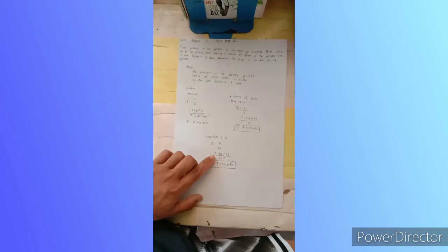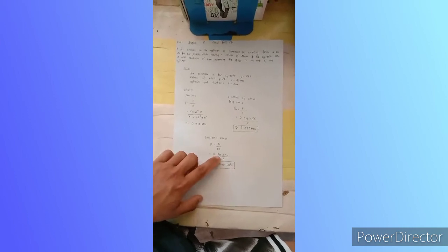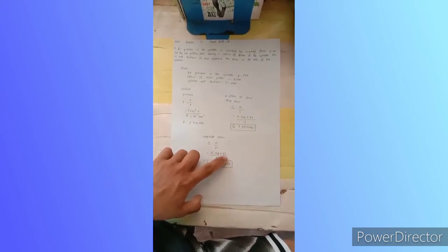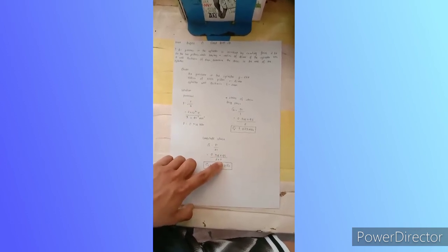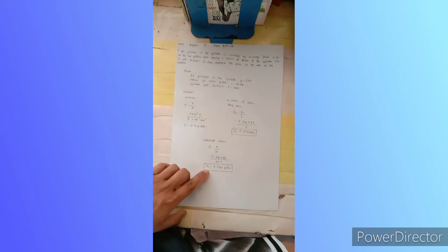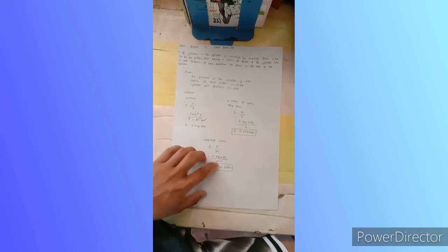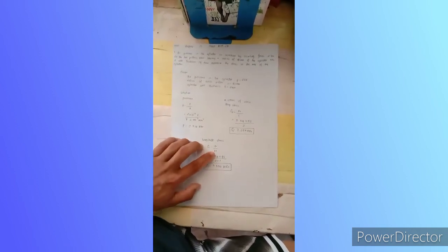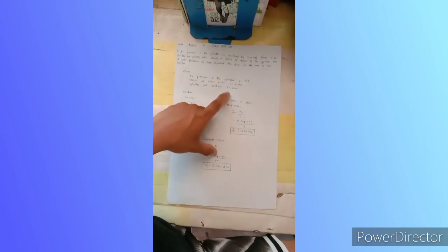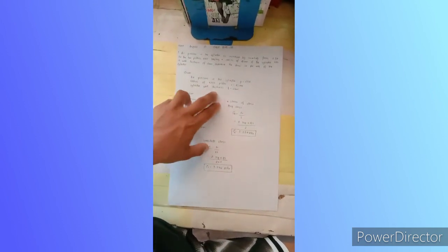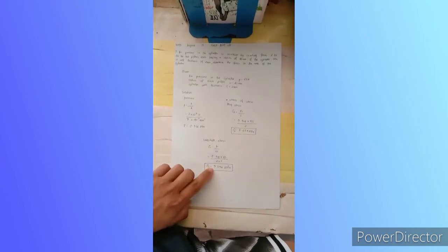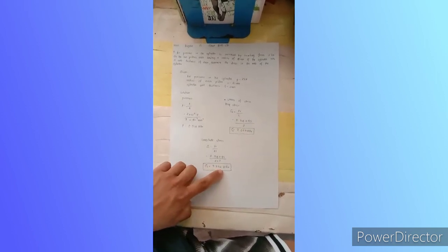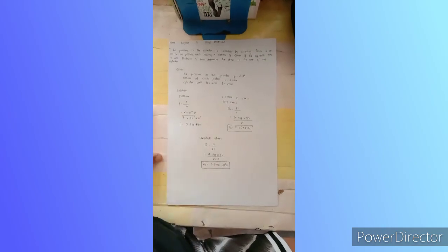So for our longitudinal stress, our stress at L is equals to PR all over 2T. So our PR is 0.314 times 45, our radius, all over 2 times 2, from the given formula, times T, our cylinder thickness. Stress at L is equals to 3.536 megapascal.